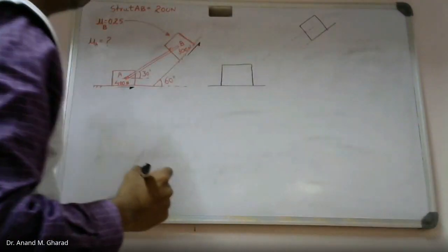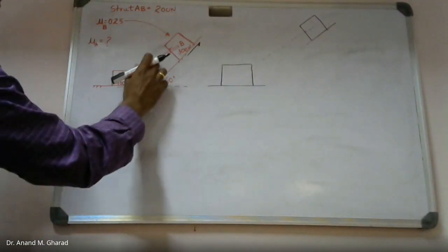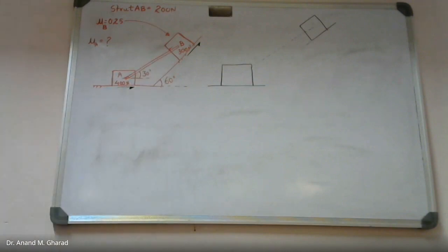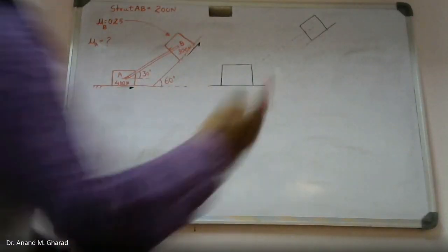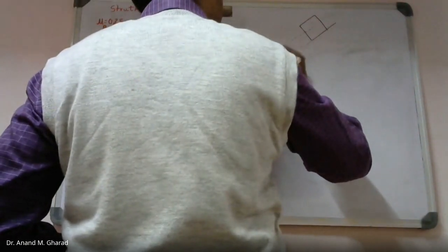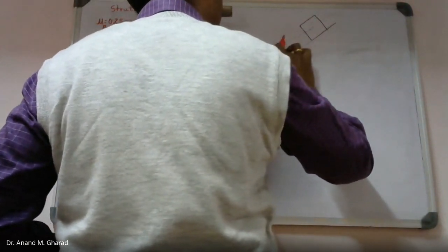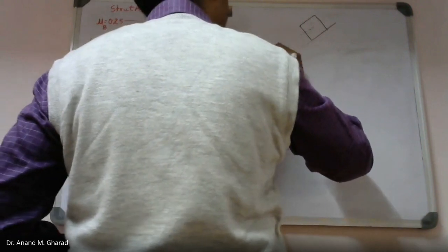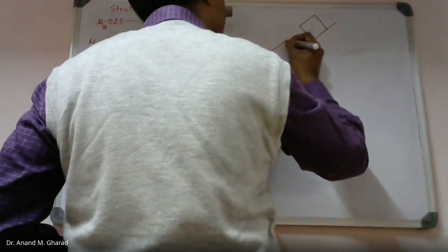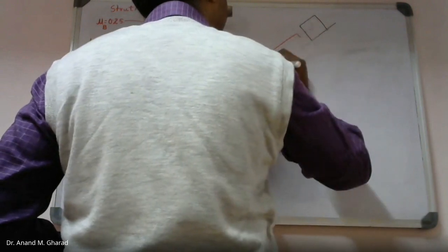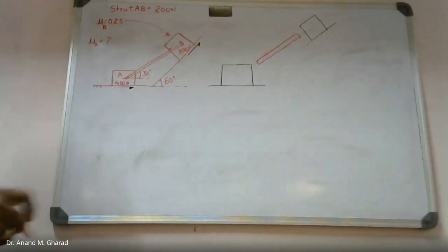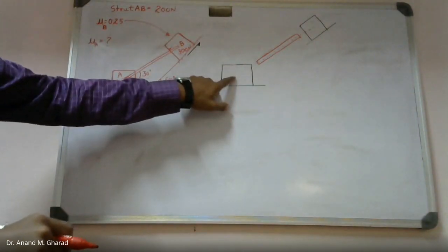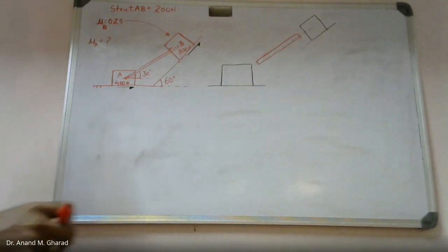Over here, one thing you should note is that the self weight of this bar or strut is mentioned. The strut is connected with the help of smooth pins, you can consider. And once we say that the connection is with smooth pins, then we will expect two reaction forces at point A as well as at point B. And what will be the direction?